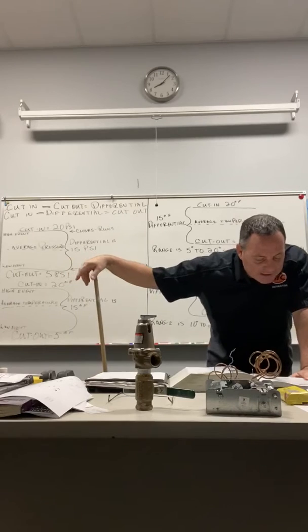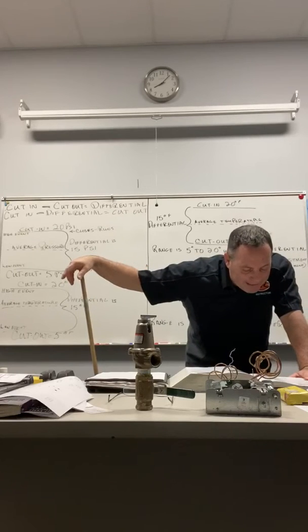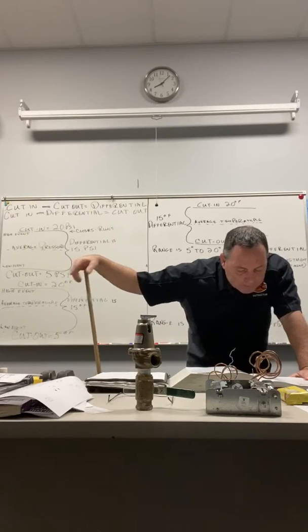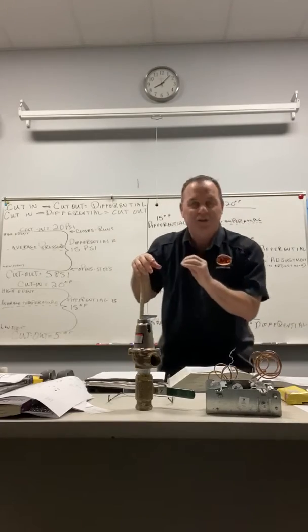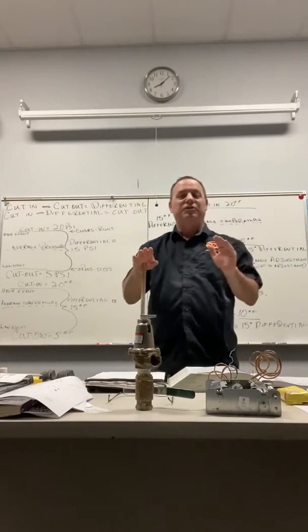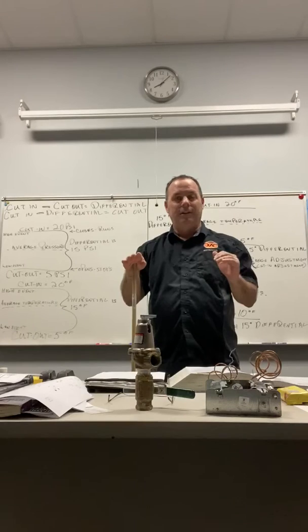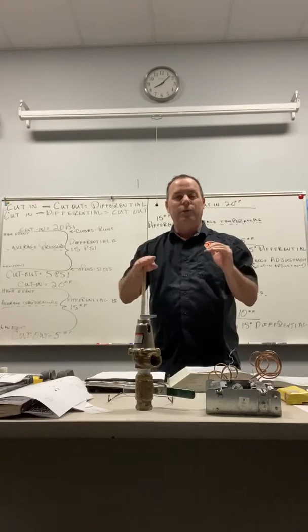If you go to page 352 on the right hand side at the bottom, it says, when used as a switch, the pressure setting at the control which interrupts the circuit and stops it is called the cutout. The cutout interrupts the circuit.